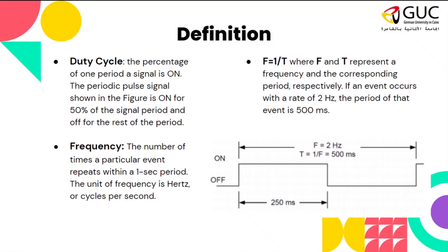We want values between 0 and 5, but our board only outputs 0 volts and 5 volts. We cannot have intermediate values. That's why we are using the PWM.